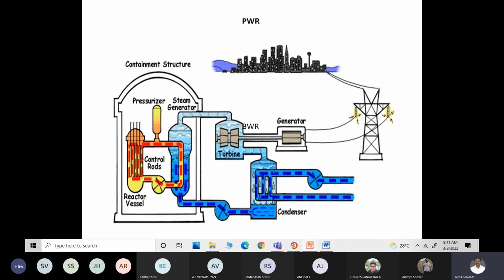Whereas in case of cold water, the heat is transferred from the hot air to the cold water, so that the water temperature rises and it becomes atmospheric temperature. The same thing happens in the steam generator as well as in the condenser. In the steam generator, the water gets converted into vapor by means of convective heat transfer, whereas in the condenser, the low pressure steam gets condensed back to liquid.